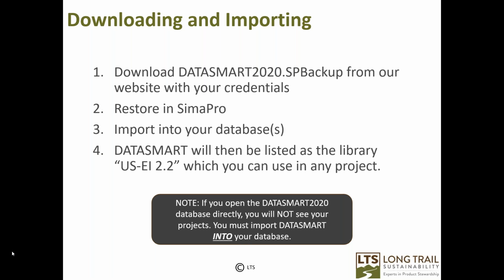To do so, users will open the database that they'd like the DATASMART update imported into, and then follow normal import procedures, starting by going under File, Import SimaPro Database. Note, if you open the DATASMART 2020 database directly, you will not see your projects. So you must first open your database and then import DATASMART into your database. And this is similar to SimaPro updates. We do provide detailed instructions, including screenshots, in our installation and update manual, and are available for technical support should you need any assistance.